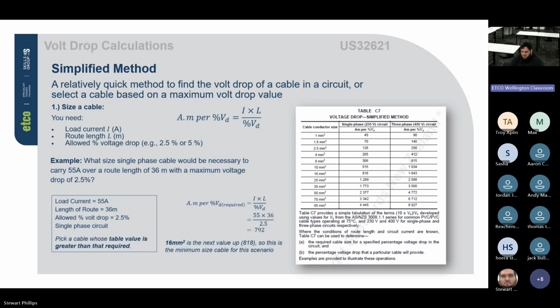You have no right to. So we then had to redirect it, which meant it was a 16 mil cable. It ended up having to be upsized to 25 because once we did the calculations of the length, we would have too much of a volt drop. So this is one example where you'd probably have to do the volt drop calculations.